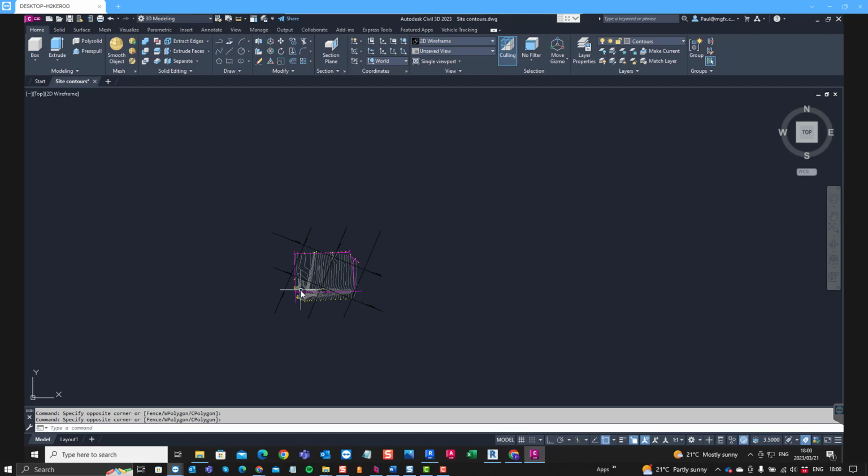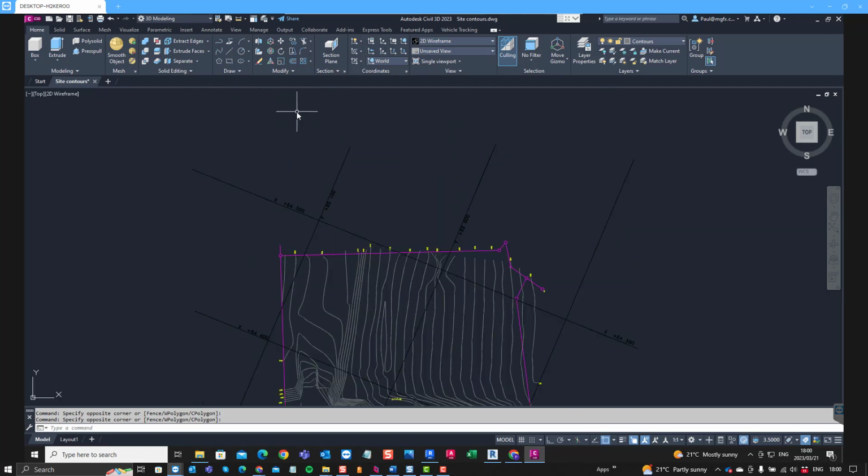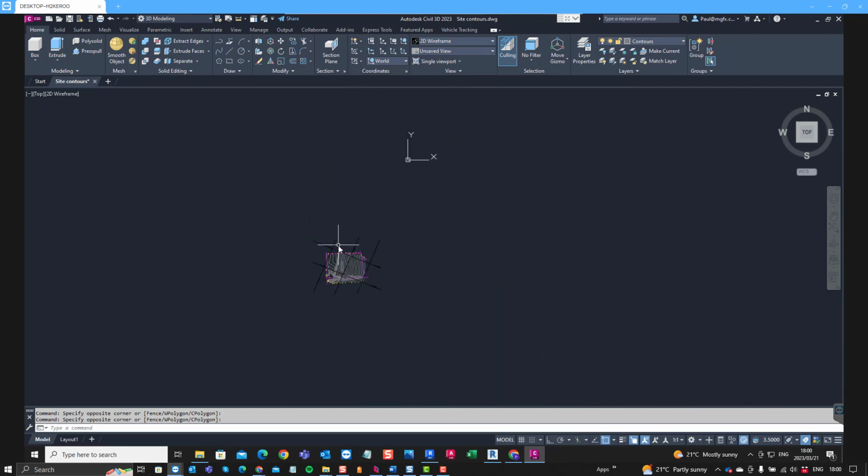Everything is set up for us here. In essence, we have some grid lines over here giving us an easting and a northing. It is at an angle to the global coordinate system within AutoCAD, but it isn't far away from the origin. Quite often that is a problem with survey files, but if you want to set up the Revit coordinate system, unless you have to interface directly with a Civil 3D published surface, which is seldom the case within a South African environment or Southern Hemisphere environment, you may put this close to the origin.